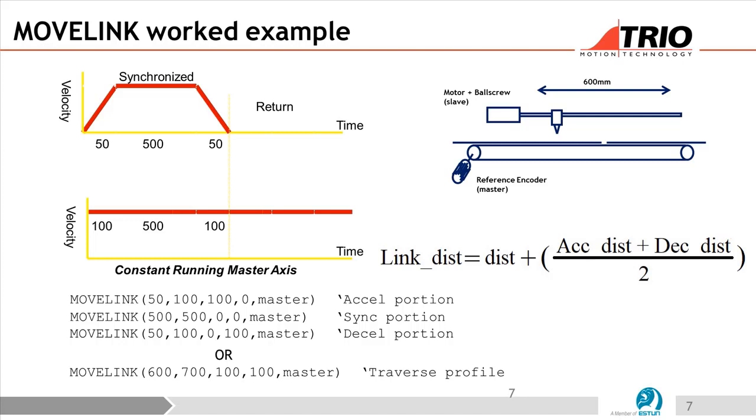And the acceleration and deceleration always have to be the same? No, they can be different. Okay. So the only rule is that there's this 2-to-1 ratio. So what you can't have is to say, well, I want it to decelerate over 100, but I want the slave to also be 100. So long as it's the 2-to-1 rule, then any will do. That's probably the reason why they are different parameters, so you can have them separated if you want.